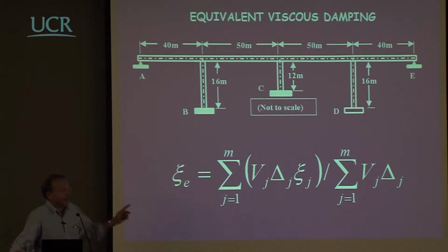That's why I wrote down this equation in such large letters, because the problem there is to find out what is the global value of the equivalent damping of the structure, considering the different parts of the structure. And the different parts of the structure could be combined in something that is similar to a combination of springs in parallel or of springs in series.